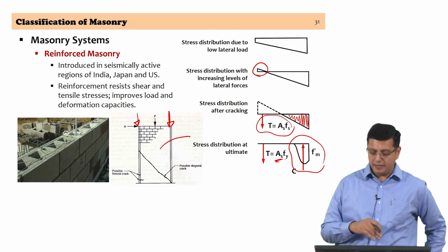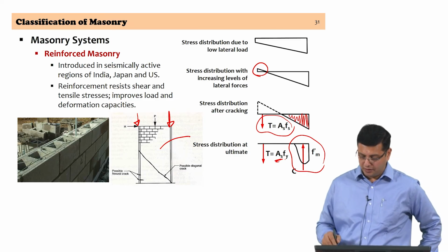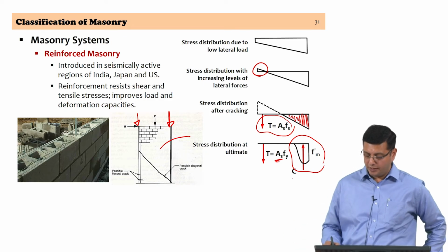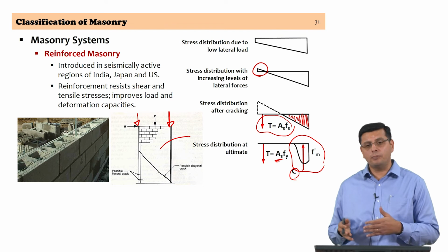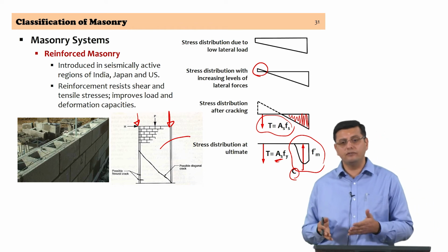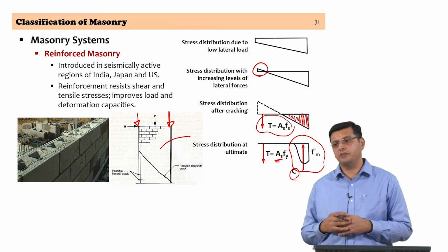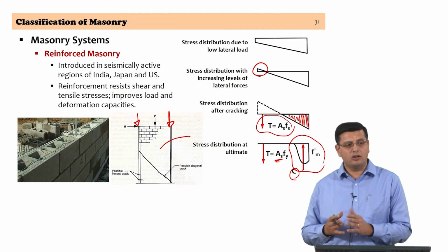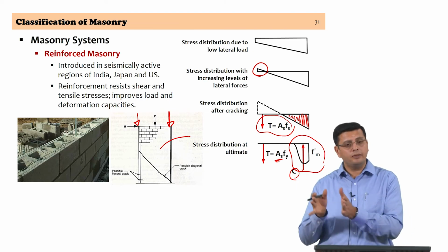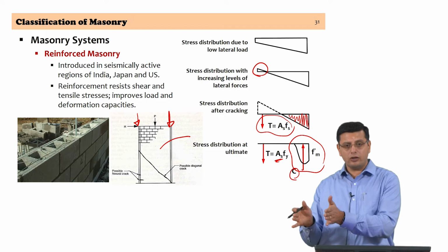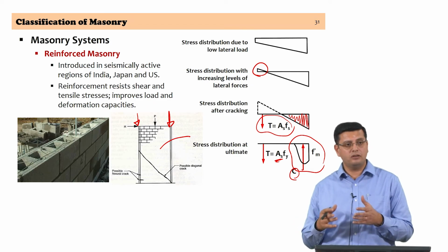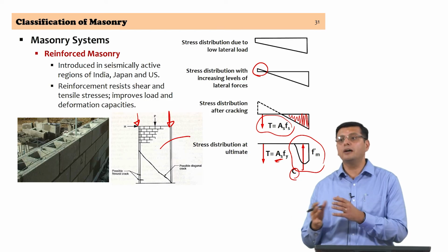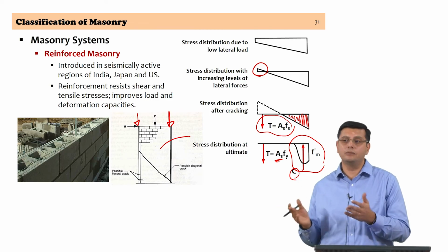All the bars should have yielded into the yield strength of the bars equilibrated by the compressive strength. Principles that we adopt in analysis of cross sections in reinforced concrete are adopted in masonry with a conscious effort to understand how the masonry block and the grout which is within the masonry block may work differently if they are of dissimilar materials.